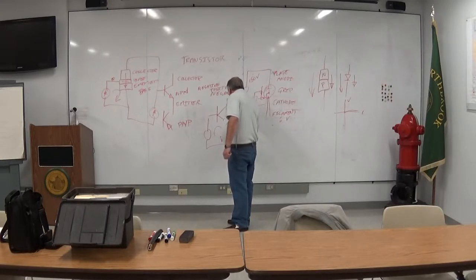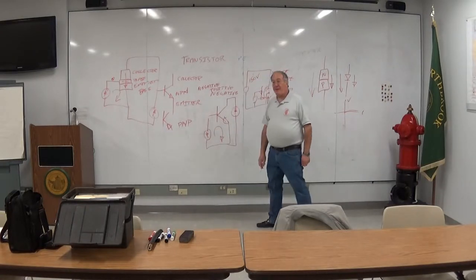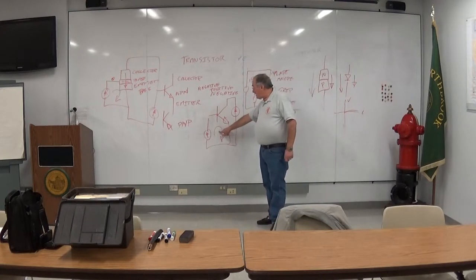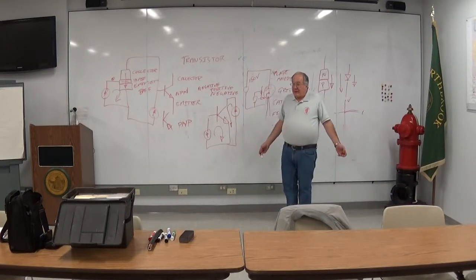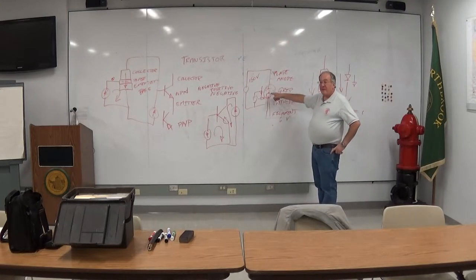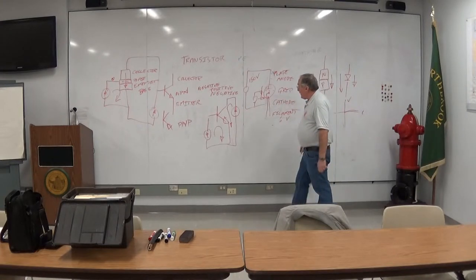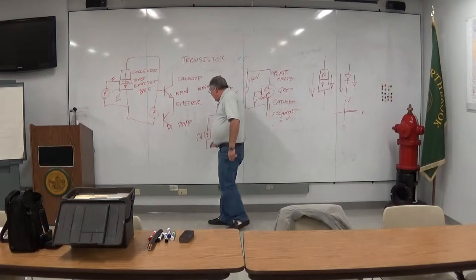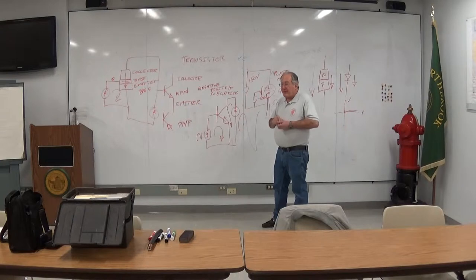It goes in this path, and this is many times this, you have an amplifier. This guy's small current flow affects this guy's large current flow. And what an amplifier really is, not so much something that produces power, but regulates power. It basically lets a small voltage or a small current make a larger voltage or a larger current result from it. So if you start putting in small signals like this, you can get some pretty big signals coming out the other end. And that's why the transistor is so useful.